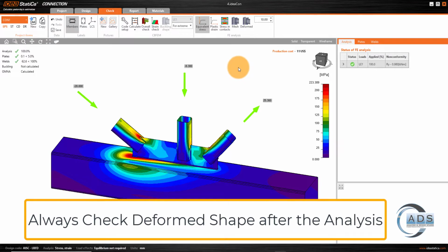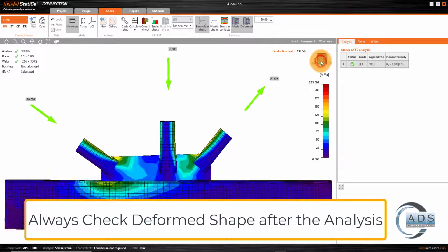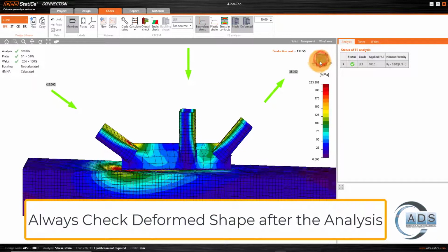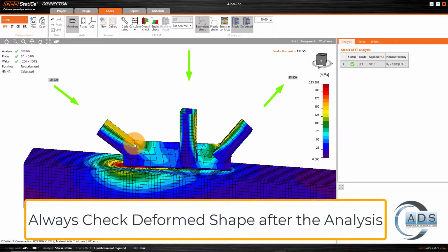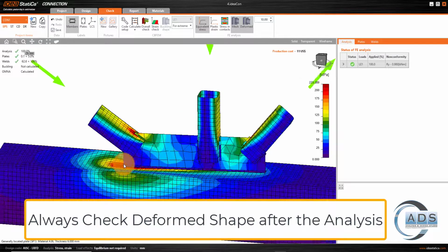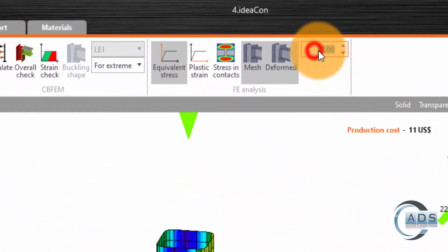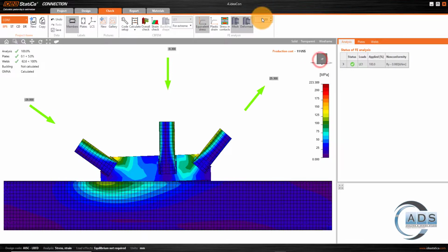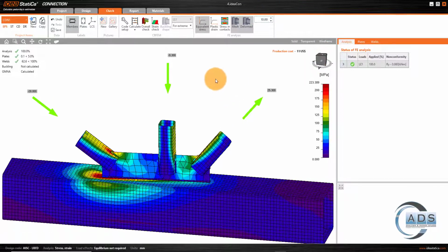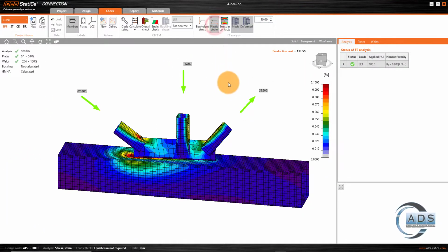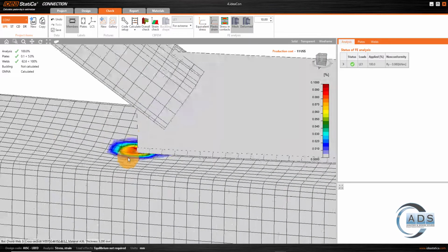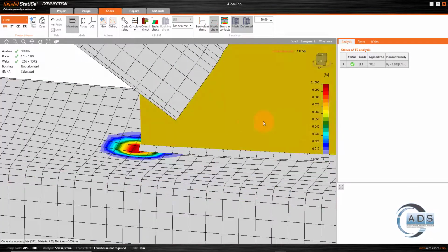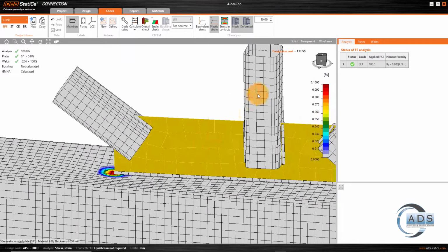The deformed shape is very important for any structural analysis. So just go to mesh and click on deform, and we can see that the deformed shape is predictable. Since this is a compressive load, it looks something like that. This is not buckling actually, because this is a 10 times zoomed deformed shape. The scale factor is 10 times. Okay. Similarly, we can see the plastic strain. Only at this particular point do we have 0.1% plastic strain. At the other points it is actually 0.